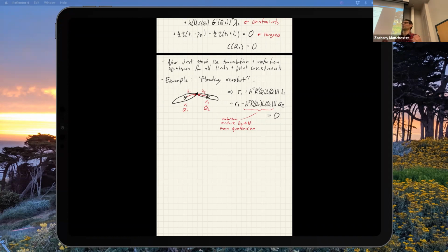I want to set some stuff equal to 0. The easiest way I know to do it, and there are many ways, the most straightforward way in my opinion, would be to take the Q1 dagger Q2 thing and get this delta Q between the joints. And then all you have to do is set their X and Y, depending on how I define this. If I define this to be the body Z axis, then I just set the delta Q's X and Y components equal to 0. That's the constraint. For a quaternion that's actually easy, because inside there is basically an axis-angle thing, so I just pick out the X, Y components from that and set them equal to 0. That makes sense.